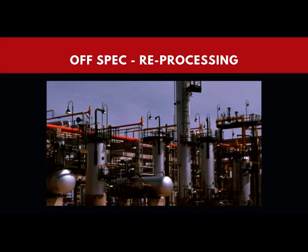The next way, if blending is not possible, is to reprocess. For example, H2S presence in LPG is a test for the LPG product. If H2S is present, then even if you blend it with pure LPG, it is not going to get diluted. Here the only way is reprocessing.